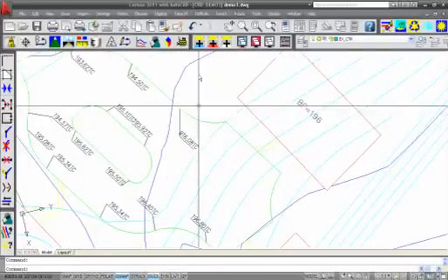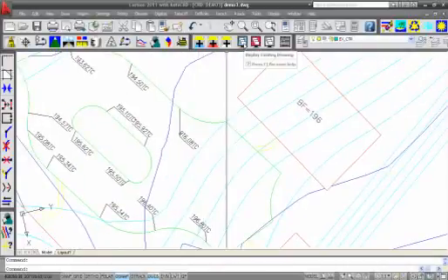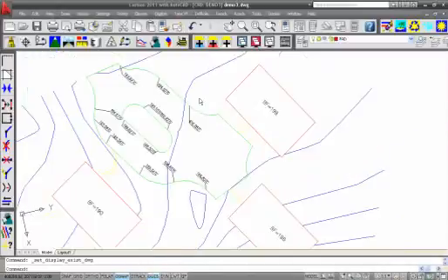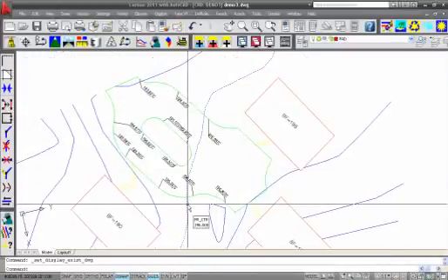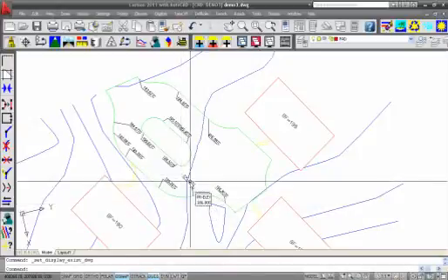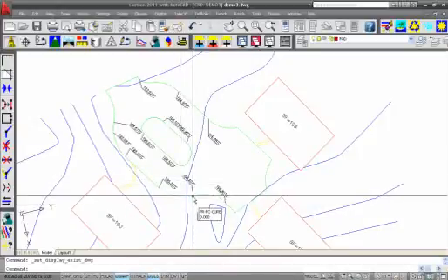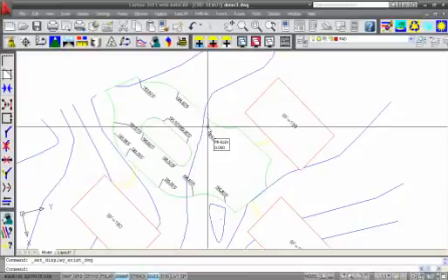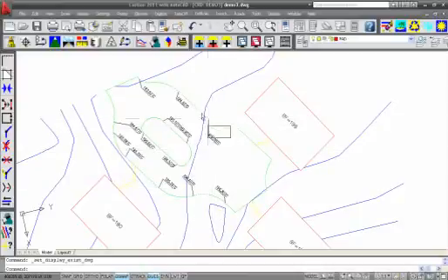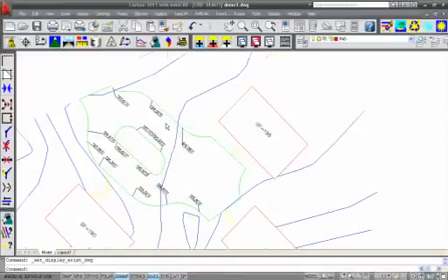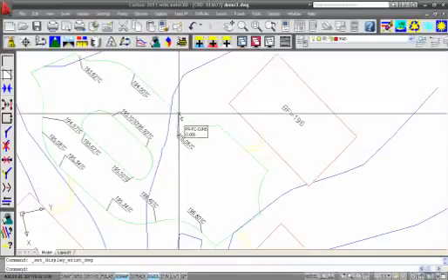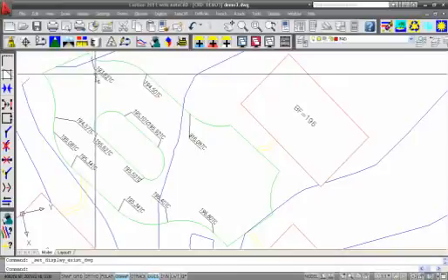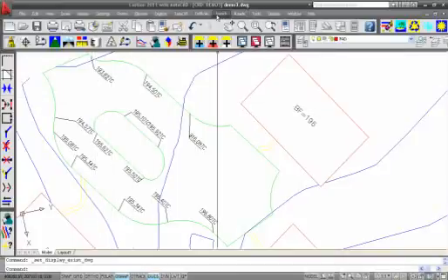We have two different sets of information. Let me turn off the existing contours. So we want to elevate this line work, and we have a contour line going through here and the label defining its elevation. Before, we would have to elevate by one process or the other, either the contour lines or the label. We now have the ability to do both of those at one time.